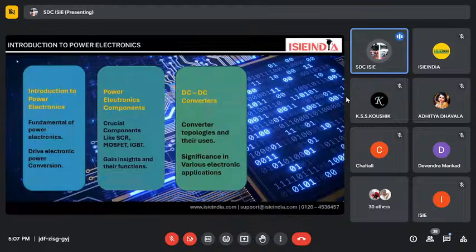But when we are talking about throttle connection, the Hall effect sensor, we are giving 5 volts. At the same time, the controller has an algorithm to give switching device connections along with the DC to DC converter itself, to step down to 5 volts, because essential equipment like the linear Hall effect sensor or minor IR sensors work at a very low voltage. So we have to step down the voltage.